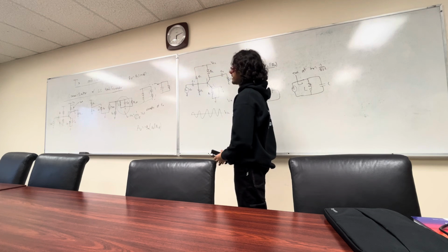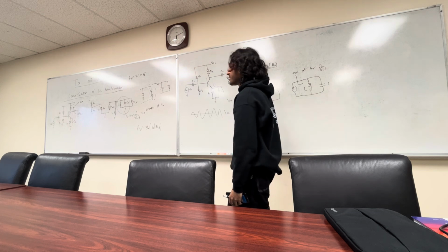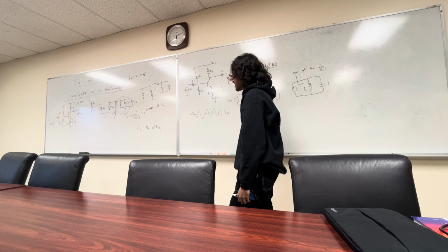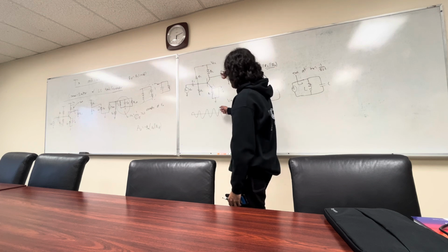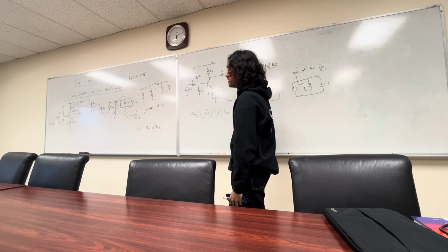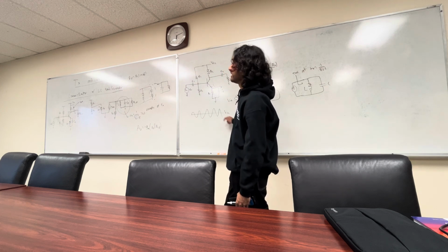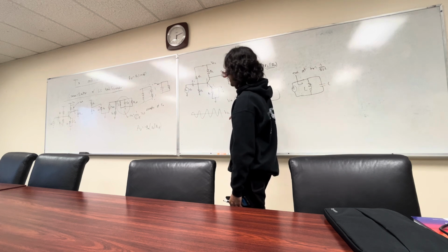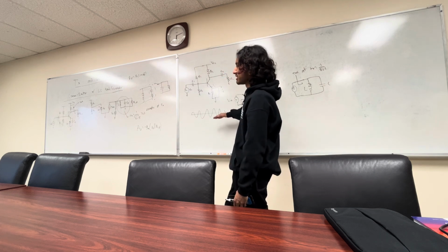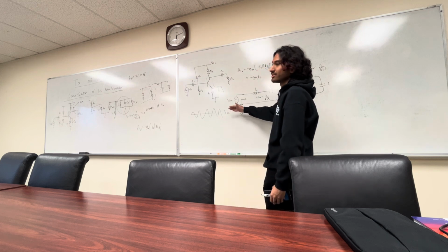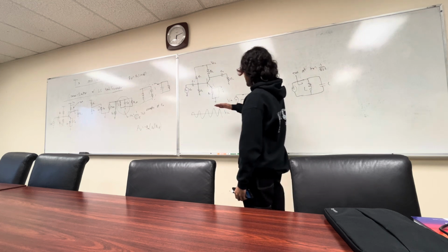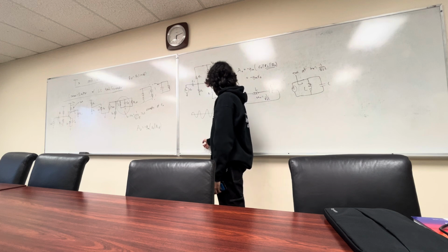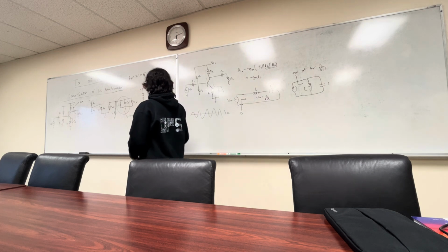So this is where looking into your maximum CE spec on a transistor is important, because if you're going to use it for an amplifier in this situation, you have to make sure this voltage doesn't go too high, at which point get a better transistor, if you're very keen on using this topology. So our signal does go above and below VCC, because we're biased at VCC, and we expect it to be symmetrical because it is an RF signal, sinusoidal, so power 0. Okay, so there's that.